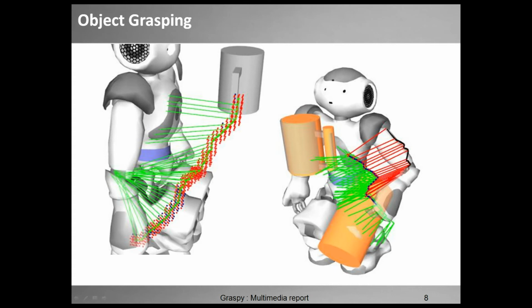Since planning in 6D is very expensive, my A-star-based planning algorithm initially only uses the 3D area grid and ignores the lower arm direction and hand orientation. Thereby, nodes to be evaluated are checked for reachability and obstacle collision in order to calculate the heuristics only for verified nodes. In this process, nodes with more suitable lower arm directions are rated better than nodes with greater deviations from the lower arm goal direction. The output from the planning algorithm is a list of waypoints through the reachability map that is converted into a Bezier spline.